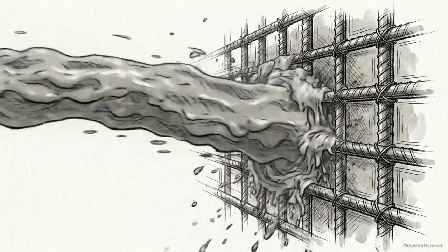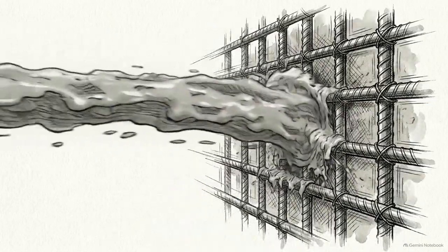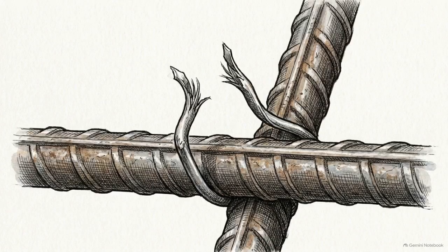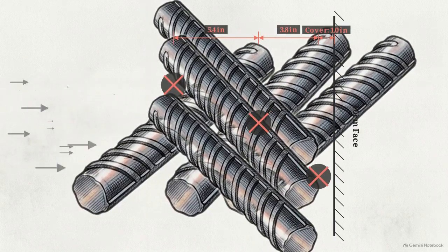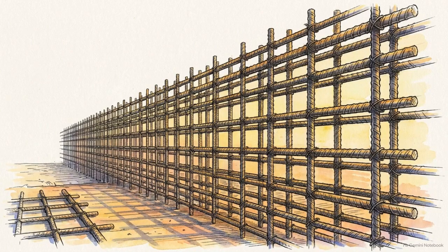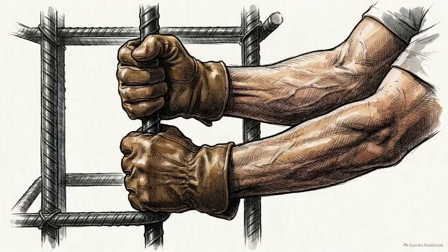Encapsulating that steel requires the cage to absorb immense kinetic energy. When a high-velocity stream of wet concrete strikes a surface, the impact is violent. If the reinforcement cage is loosely tied or only standardly secured, that kinetic force causes the steel to shudder and shift upon impact. The moment those bars move under pressure, the carefully measured spacing, alignment, and cover metrics are immediately compromised. A cage that appears compliant during a quiet pre-placement walkthrough will fail during shooting if it lacks absolute rigidity. A static visual inspection is inadequate. The inspector must evaluate the reinforcement's capacity to withstand a dynamic impact without shifting.